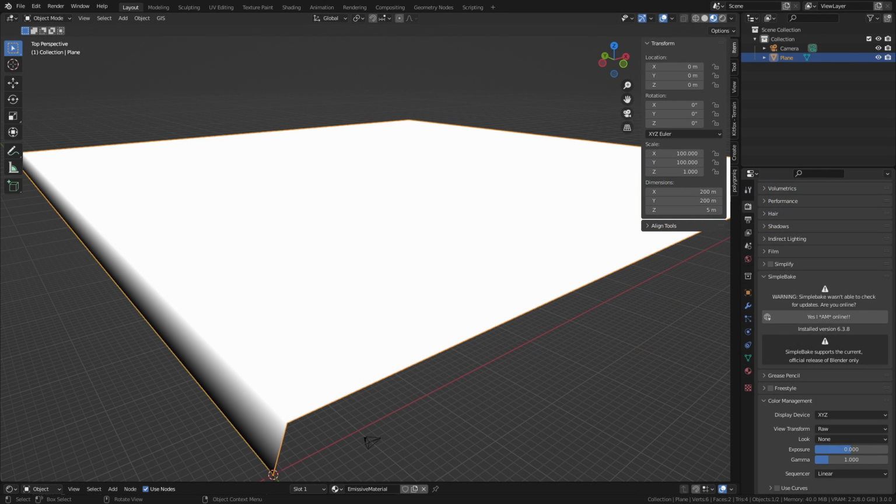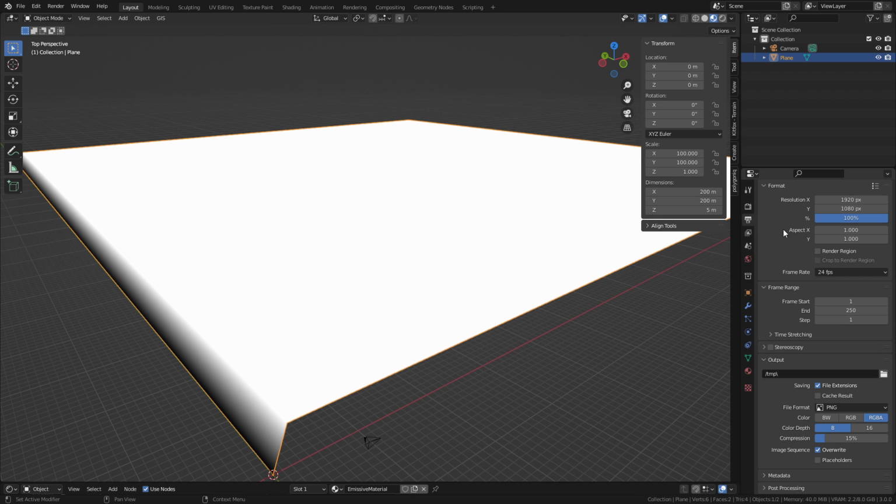All right, the next step, we need to change our output. When we start rendering this height map, we need to tell MX Bikes this has to be a power of 2 plus 1 pixels. So if you are going to do a 2K height map, that needs to be 2048 plus 1 pixel equals 2049. So let's go ahead and do that. We're going to come to our output here.